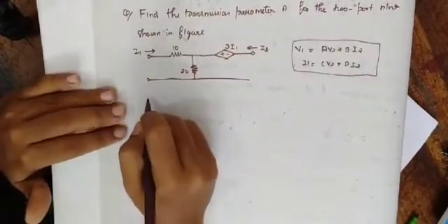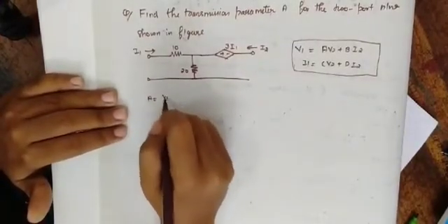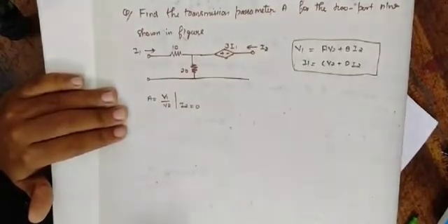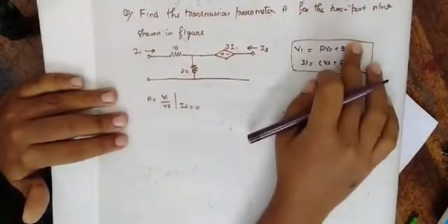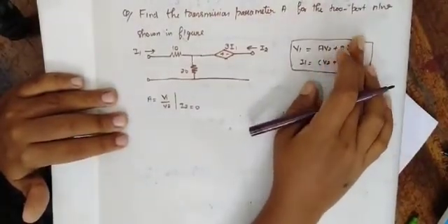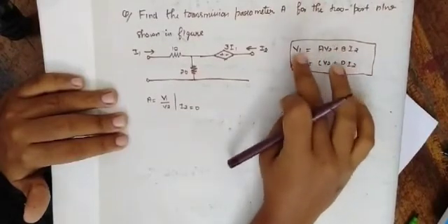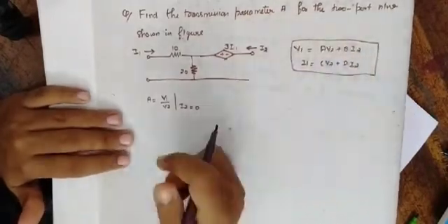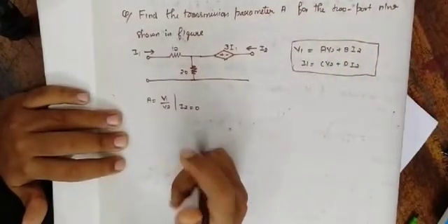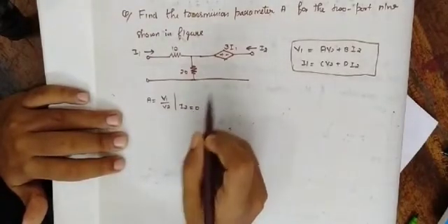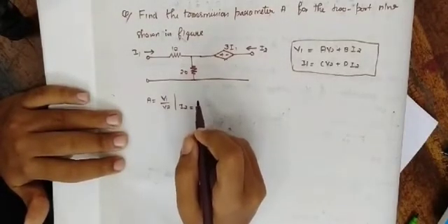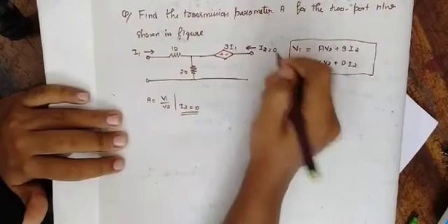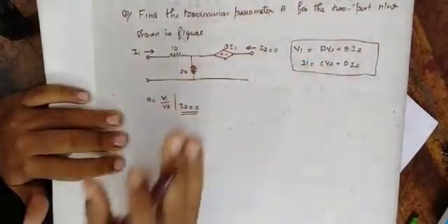So to find out A, the equation is V1 divided by V2 when I2 is equal to 0, okay. So when I2 is equal to 0, this term will be cancelled out. So what will be remaining is V1 is equal to A V2. From there we will get A is equal to V1 divided by V2, okay. And from the figure itself we will have to find out our A. So it is given that I2 is equal to 0. So only current present here is I1.